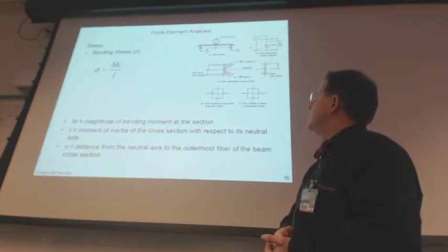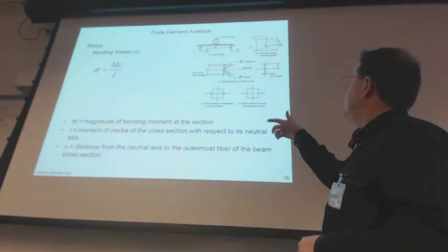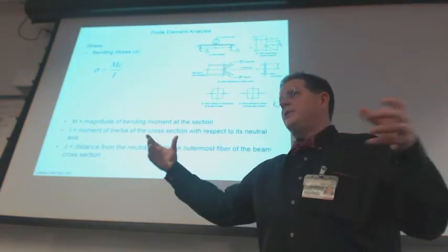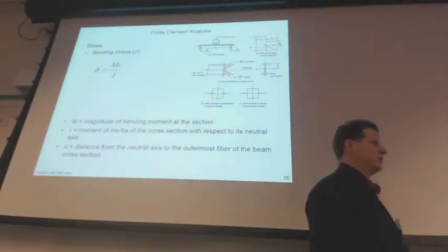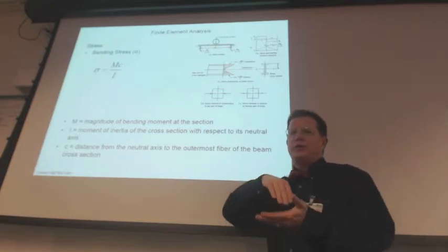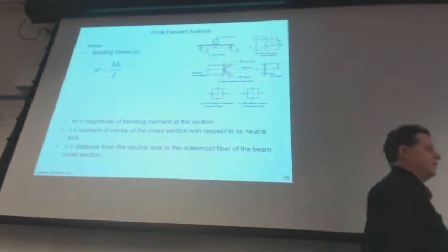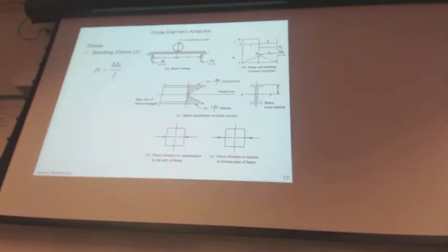So bending stress, moment. Anytime we have bending in a beam or any kind of shape that has more than a 10-to-1 ratio in length versus height, and we have a force somewhere in the middle, perpendicular to the axis of the device or the object, then we have bending, and we're going to determine stress with MC over I. Just more examples for that.